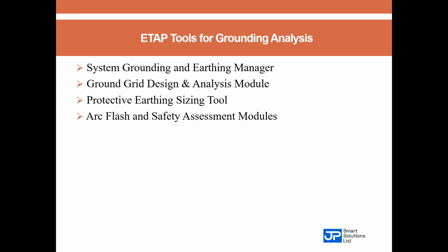We have a training upcoming which is on solar PV systems. In solar and inverter based systems, proper grounding defines the system's voltage reference. Without it, the system can float, causing unpredictable behavior and communication errors in controllers.